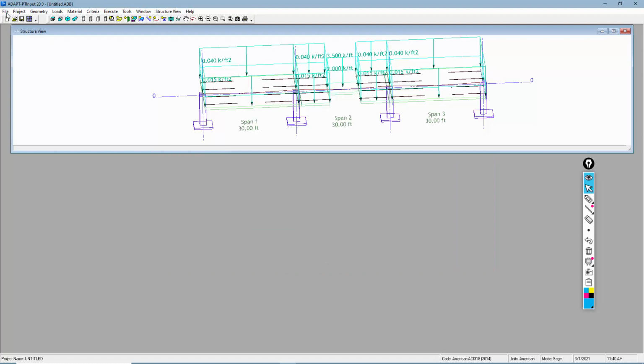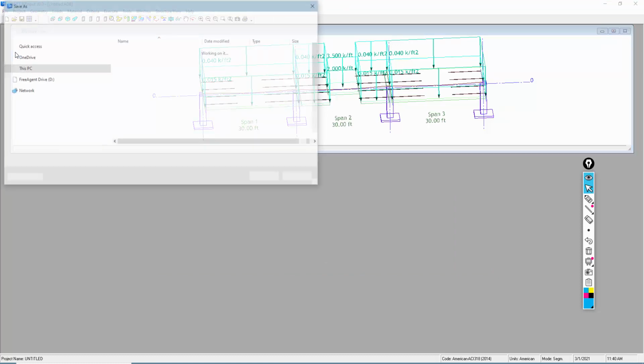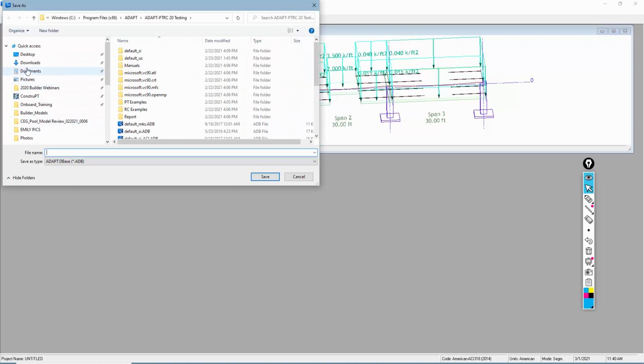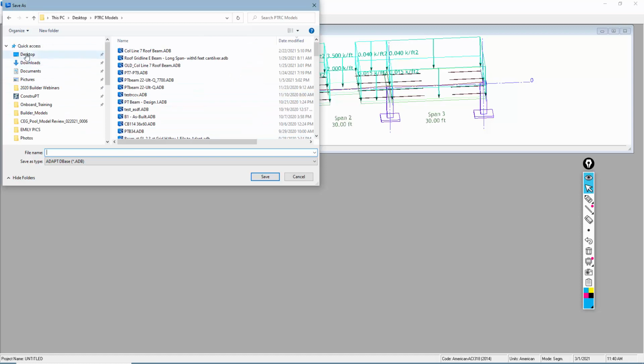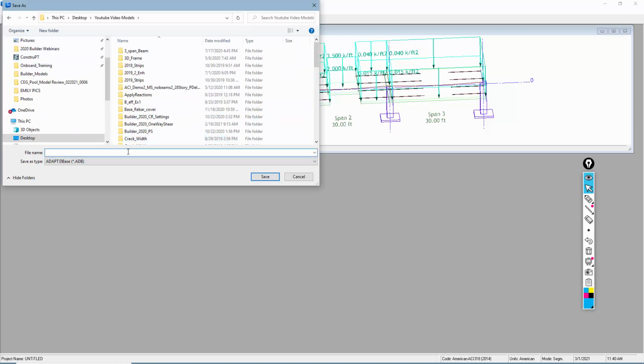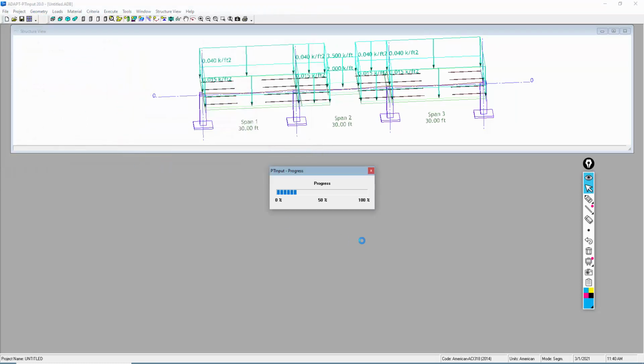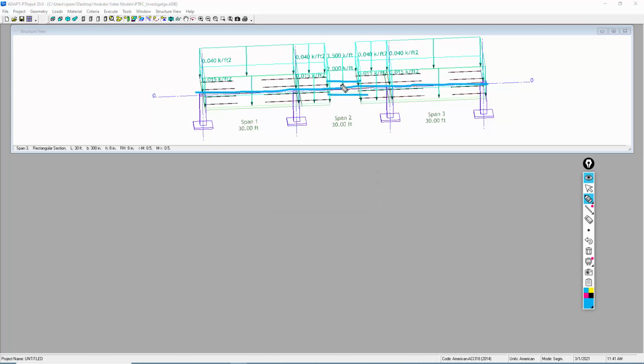Once you've entered the input, we're going to select the option to save the file. So we'll go here and just save this. All right, and we're going to assume that for this particular slab, this might be a banded run. So all of our cables are kind of along the center line. That may have limited them actually cutting out or cutting further, let's say, into this zone. We need, let's say